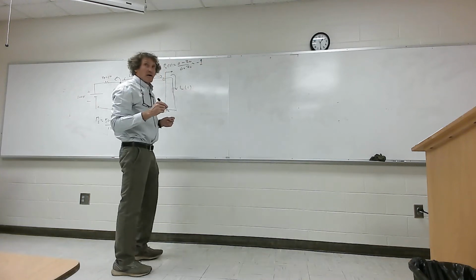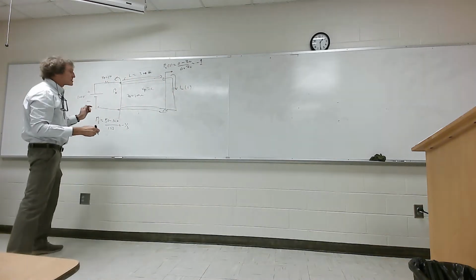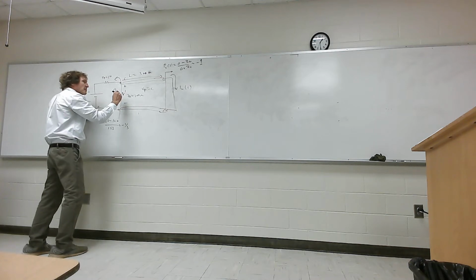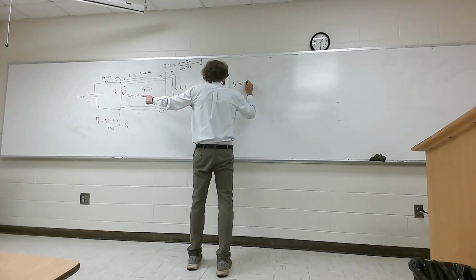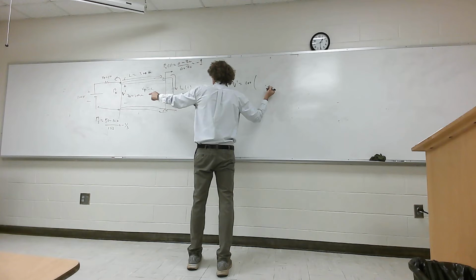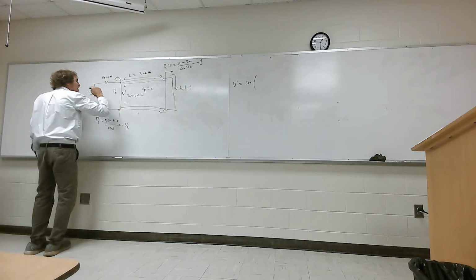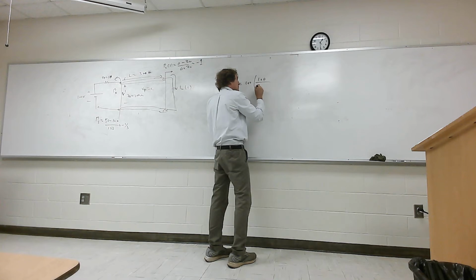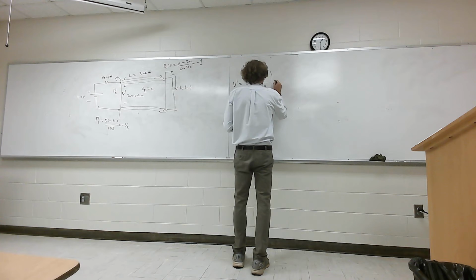Okay? Now, if I want the current here, I first have to get the voltage waveform incident on it. So I need my V prime as before. So what's V prime going to be? 100, correct? Times what? This is 50, by the way, if you can't read my writing. It would be times 100 over 50 plus 100, over 150, right? Because it would be 100 plus 50, correct? So that's 66.667 volts, right? Correct?